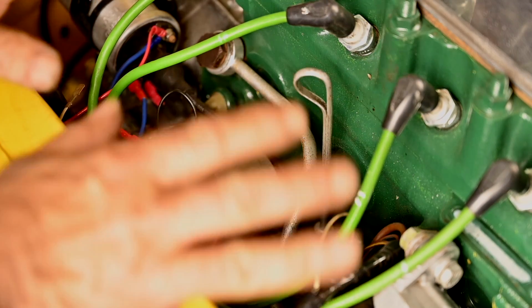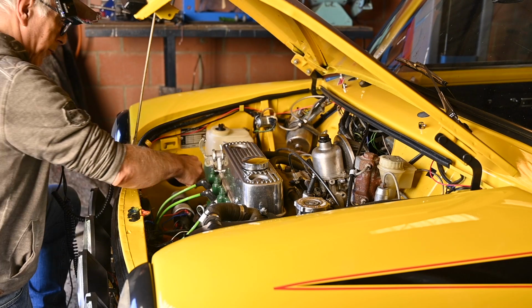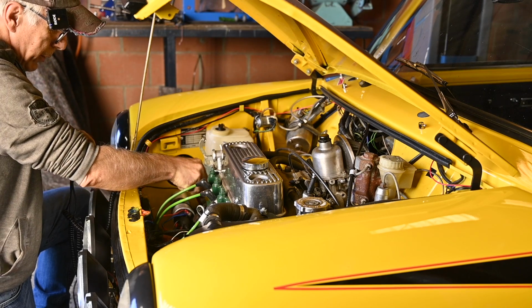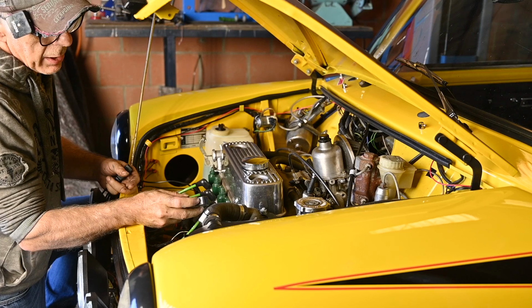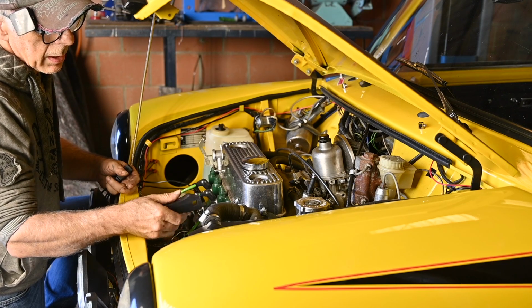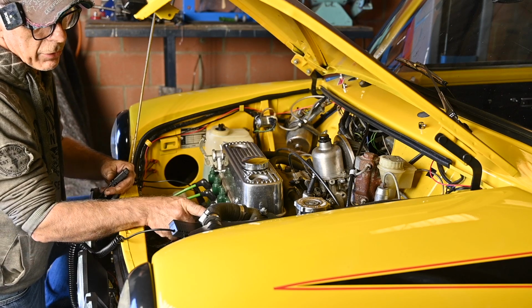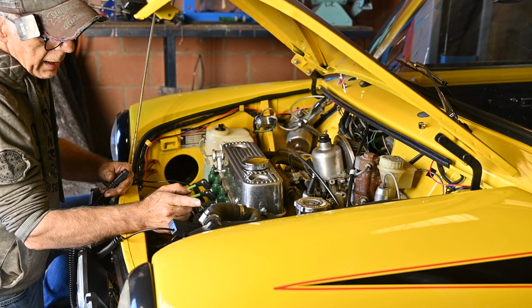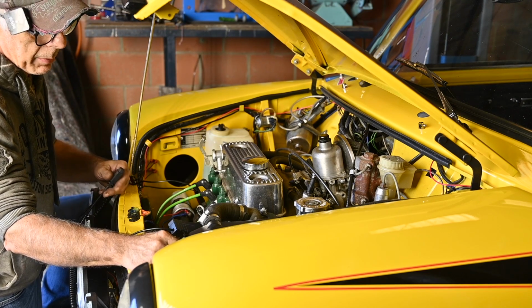Now we need to hook up my strobe light. So the strobe light is going to go to the plus 12 volts, and I'm going to pick it up from the starter relay, and the other clamp is going to the ground to make sure you have a good ground. And then you have the clamp that's going to pick up the spark, and you typically have an arrow on it pointing towards the spark plug. So put it on like that on the first cylinder, and on the Mini the first cylinder is the spark plug closest to the radiator, and then we are about ready to start it and have a look inside with the strobe light to see what's going to happen.